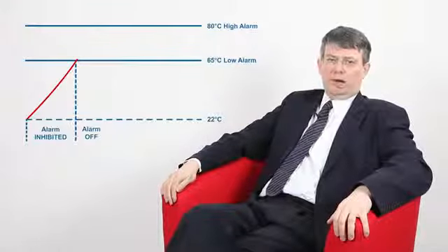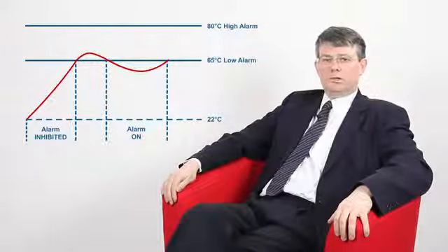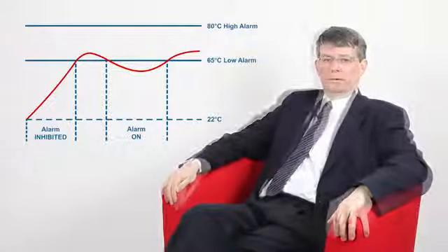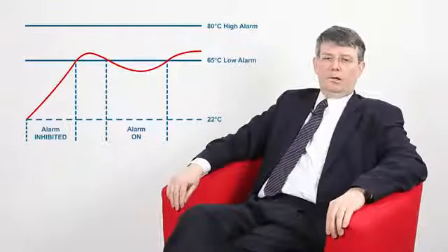With the inhibit function active, the alarm will not actually activate until the process has first got into a condition where it would not be active and then move back into the active condition again. Only from that point onwards does the alarm activate and work normally. The high alarm that you set at 80 degrees C would already be in the non-alarm state as you powered up, so wouldn't be inhibited, but then of course it wouldn't be active either, so that's not a problem.